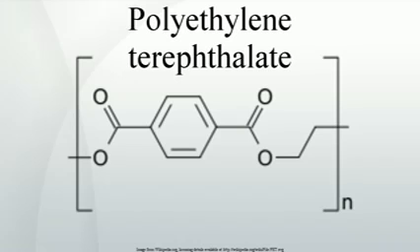In addition, with this way of processing, a chemical decomposition of the hydroperoxides is possible by adding a corresponding P-stabilizer directly when plasticizing. The destruction of the hydroperoxide groups is, with other processes, already carried out during the last step of flake treatment, for instance by adding H3PO3. The partially glycolized and finely filtered recycled material is continuously fed to the esterification or pre-polycondensation reactor. The dosing quantities of the raw materials are being adjusted accordingly.